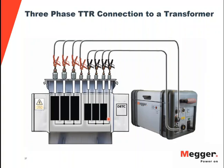Now let's talk about the winding resistance. It goes back to the other question that was asked, that I would do H1-X1, and I would also do H1-H0 to take into account all the bushing connections. When I'm doing the testing on the secondary side, which is delta winding, you would notice that it will take a lot of time to stabilize the winding because it's a delta winding, and that too on the secondary side. Secondary delta windings are the biggest challenge. So make sure that you allot enough time to get a stable reading.